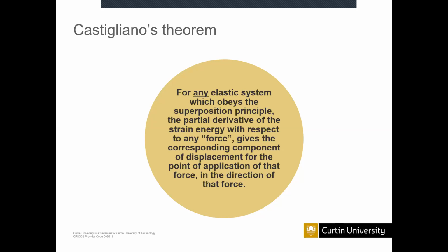In the first few cases, we are not going to use a dummy load, because they will ask the deflection where the load is available, and in this presentation also they will use it that way. But in the next stage, they will ask for the deflection at some point where there are no loads. Then you need to use a dummy load. The point of application of that force, in the direction of that force.